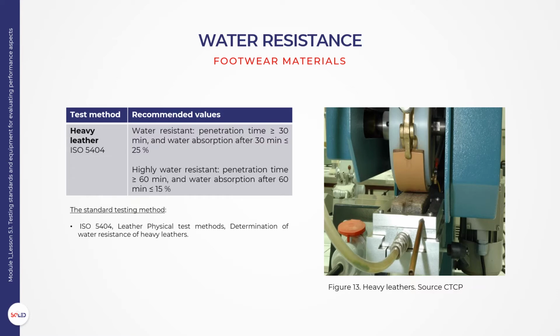The recommended values are as follows. A leather is considered water resistant if for a penetration time higher than or equal to 30 minutes the water absorption after 30 minutes is 25% or less. And it is considered highly water resistant if for a penetration time equal to or higher than 60 minutes the water absorption after 60 minutes is 15% or less.